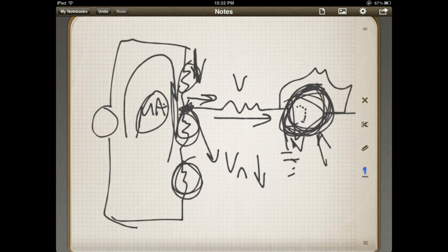That's why voltmeters will come in different ohmages. They have different input impedances, because I've had that happen with a meter where you're trying to measure something that's in nanoamps and the meter is in mega ohms. Well, when you get down to nanoamps and stuff, a mega ohm is not going to cut it. It's going to rob too much current from the circuit. You need something that's in giga ohms so that way it robs